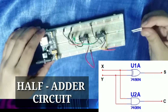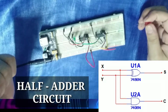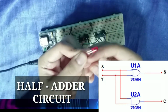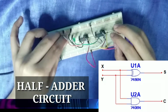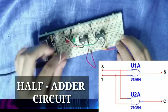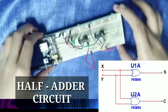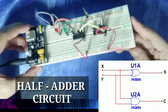Our output for the carry from the quad gate is the red LED here. So let's connect it here. And of course, do not forget the grounding for our output for carry. So this will be our circuit for the half adder, which is our part 1.